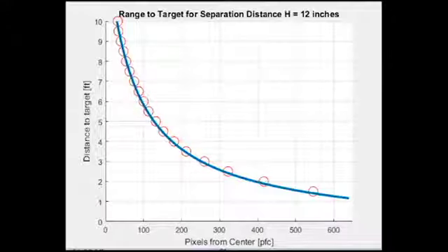This graph shows the measured and theoretical values after calibration. The red dots represent the measured values and the blue line represents the theoretical values. After changing the correction factors, they seem to match very well. The device was kept a fixed distance from the target. A tape measure was used to measure the horizontal distance of each scan. The device was then used to scan a vertical line at each horizontal location.